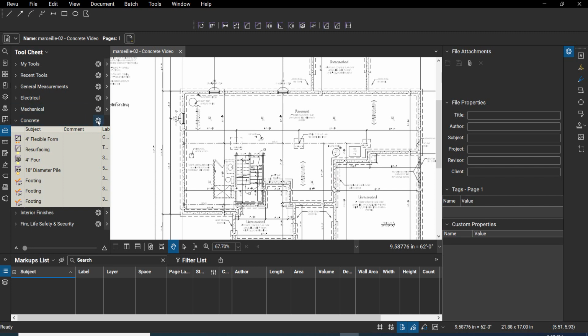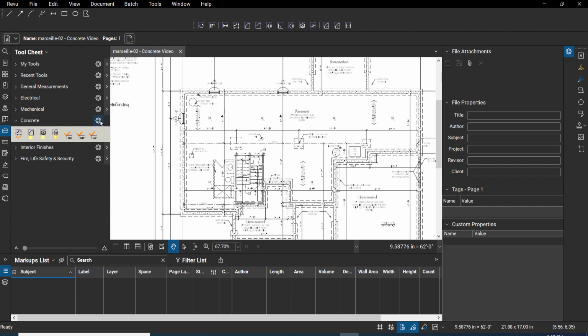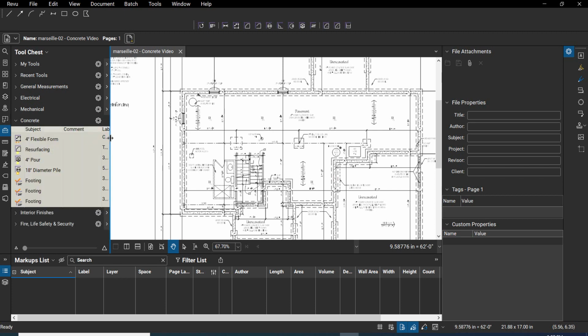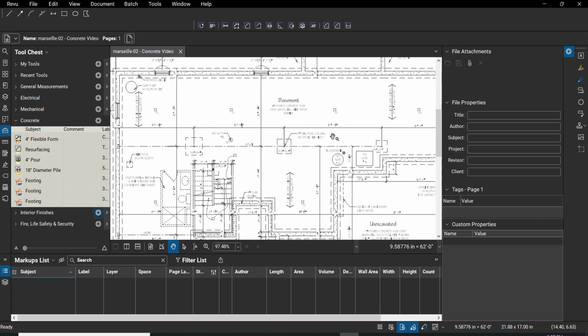So when you open these toolbars, if you click on the settings button there, it's probably set to the default symbols. You can go to detail and it gives you a little bit more information, okay? You're only going to have one footing. So what I did is I duplicated it twice and edited them so that I would have them already there because my footings are of different sizes. And in this case, we've only got 3 footings, so it's not that big of a deal, okay?